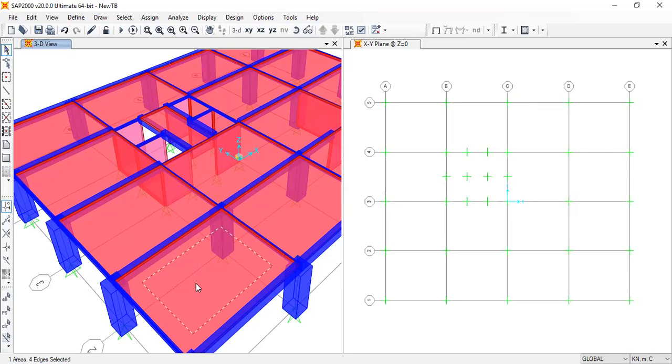which is approximately 1.25 kilonewtons per meter squared. That will also make a big change in the model. But if you use secondary beams, you have to cast additional beams, so that is laborious, right? But still, if you use secondary beams, your moments and everything will be lower, so your reinforcement will also be lower. Okay, so those advantages and disadvantages are there, right?